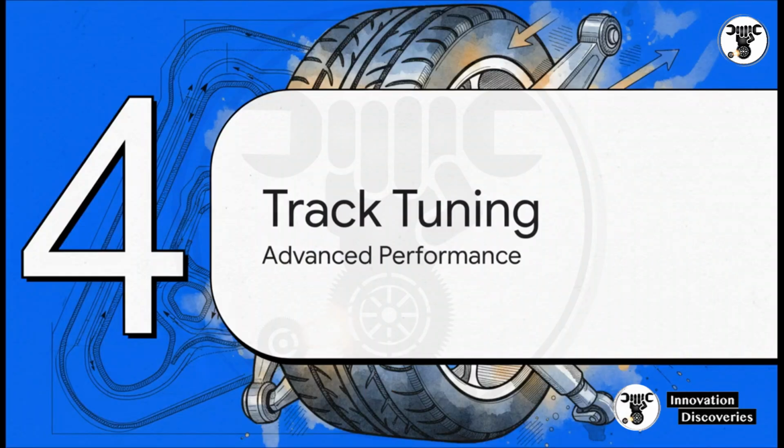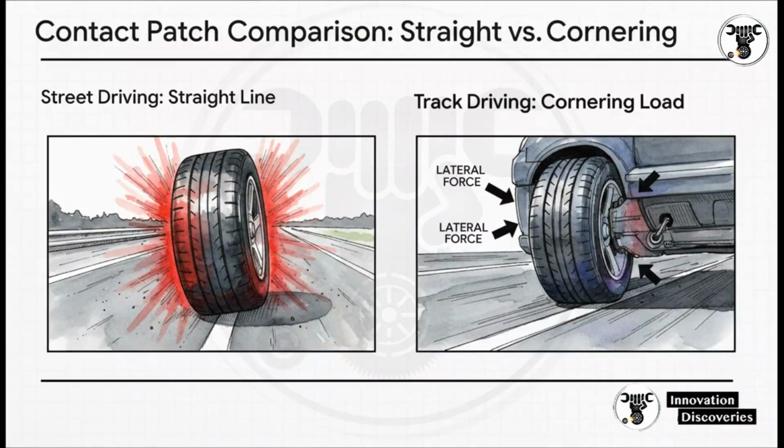Moving into Section 4, Advanced Performance and Track Tuning. This is where we toss the factory defaults out the window to optimize dynamic grip. If you're looking at a street-driven performance car, you generally want a balanced approach. We're talking around -1 to -1.5 degrees of camber, maximize caster for that great steering feel, and a slight rear toe-in for stability.